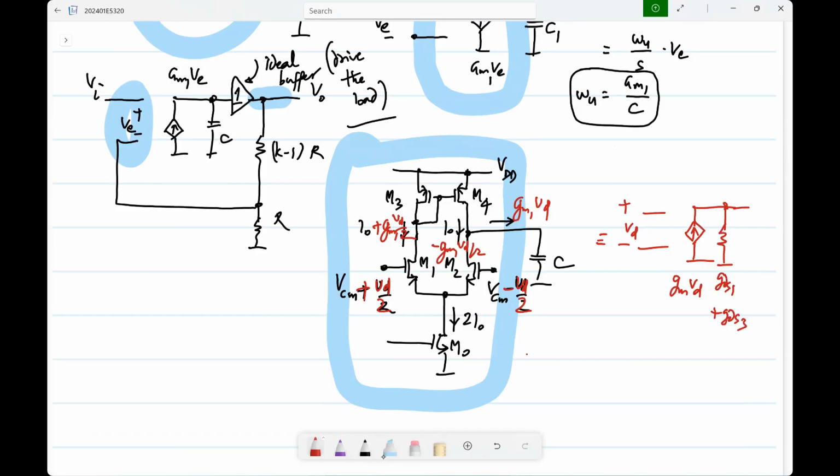Okay. So now, whenever I have differential circuits, of course, assume that M1 is matched to M2 and M3 is matched to M4. Okay. So I'll use the same notation to denote small signal parameters of these. That is, for M1 and M2, I'll call it gm1 or gds1, and similarly for M3 and M4, I'll use gds3 or gds4 to denote their output conductances. Okay. So one thing that you can expect is that you make an ideal controlled current source, but that always comes with a finite output resistance or a non-zero output conductance.